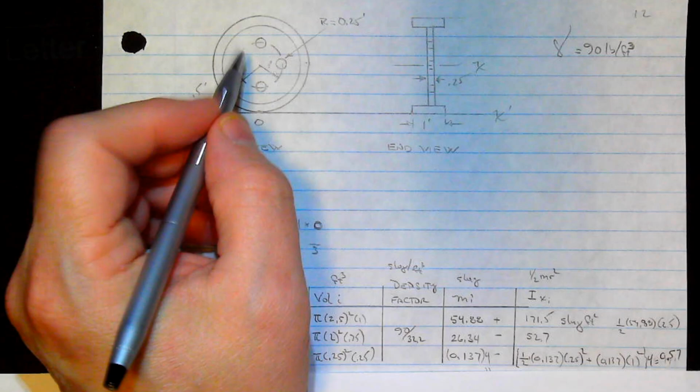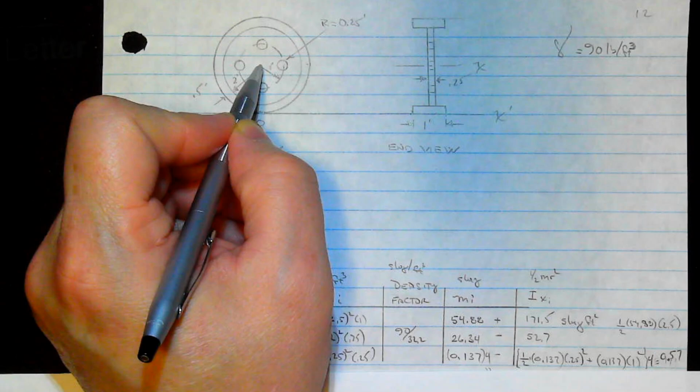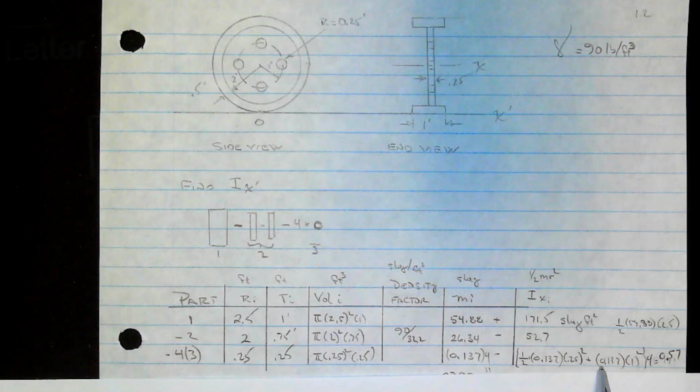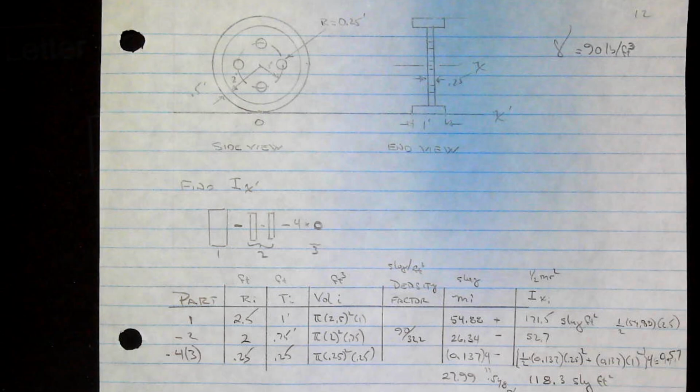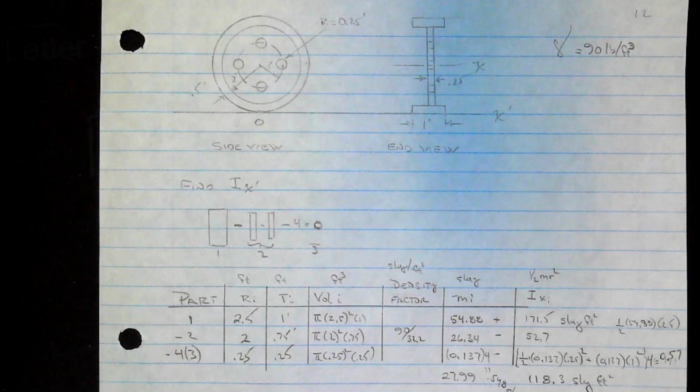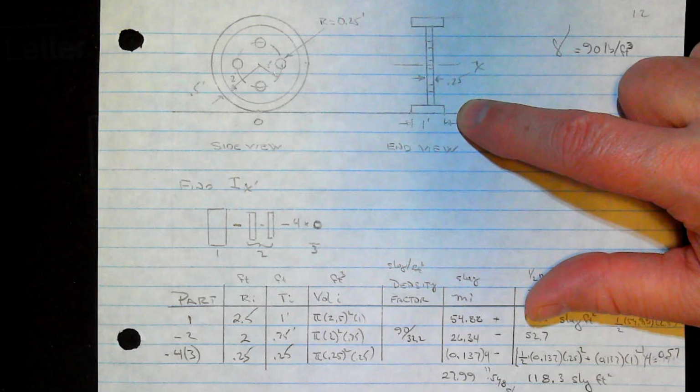The second cone, this little bitty one, if we go look up here, I'm going to bring that down a little bit, at the base, the radius of it is 200 millimeters, and the height is 333. So we go pi over 3, base 200 squared, height 333, divided by 1,000 cubed, 0.014 meters cubed.